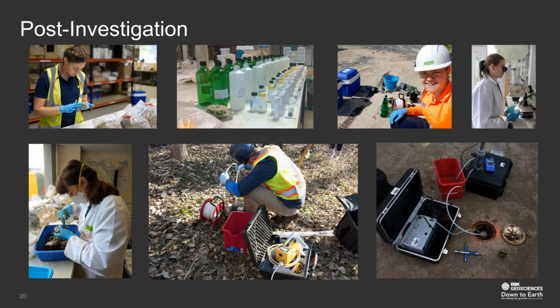Post-investigation, samples are sent to the laboratory for testing. Typically, soil classification tests are used to determine grain size, Atterberg limits, soil type, and strength to measure properties like shear strength, compressibility, and consolidation. Another post-investigation technique is monitoring, which moves us nicely onto the final section of our webinar, sampling and monitoring.